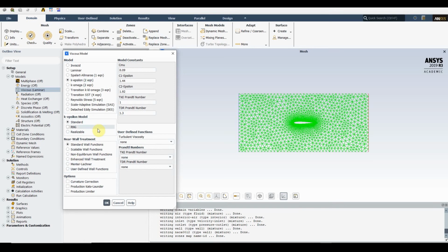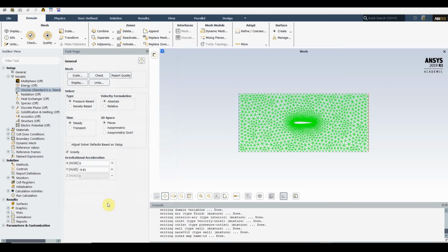It can have a detrimental effect on the simulation results if you don't understand what these are, but we do go into these a lot further in the master's program if you wish to take this further later on in your academic career. So we selected the K epsilon model. It's a steady simulation, it's not time dependent. So total gravity, viscous model, K epsilon selected.